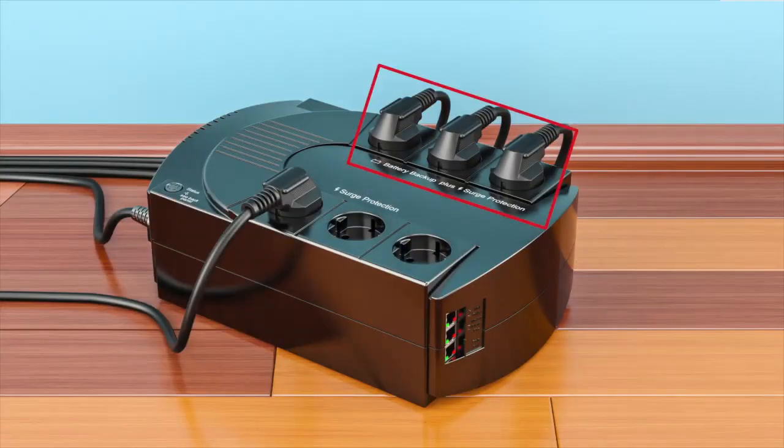First, we plug the UPS system into a wall outlet. When you initially purchase a UPS, the battery will probably need to be charged for quite some time, maybe even overnight, before it reaches 100%. Okay, so now I plug my PC into one of the protected outlets on the UPS. Be very careful with this because you'll often find that only some outlets are battery backed, and others only provide surge protection. If you plug your PC into a surge-only outlet, you won't have any battery backup.